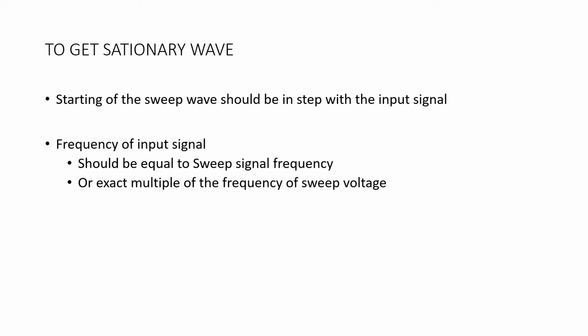If the vertical input frequency is not exactly equal to or an exact multiple of the sawtooth frequency, the waveform will not be synchronized and the display walks across the screen.